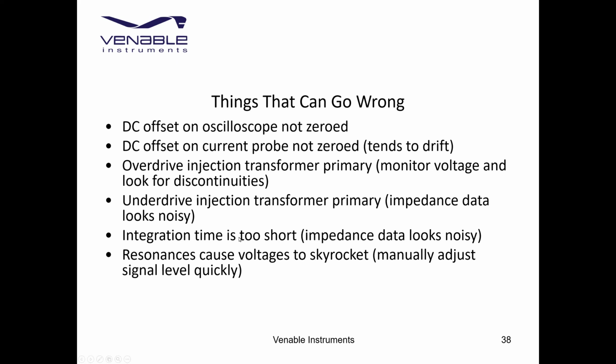So if your integration time, which is sort of the inverse of the bandwidth on a network analyzer, is too short, the notch, I'll call it the discrete Fourier transform notch, will be too wide, and you'll start getting noise. If you want it to narrow, you have to take more data and spend more time on each data point in the measurement for rejection.